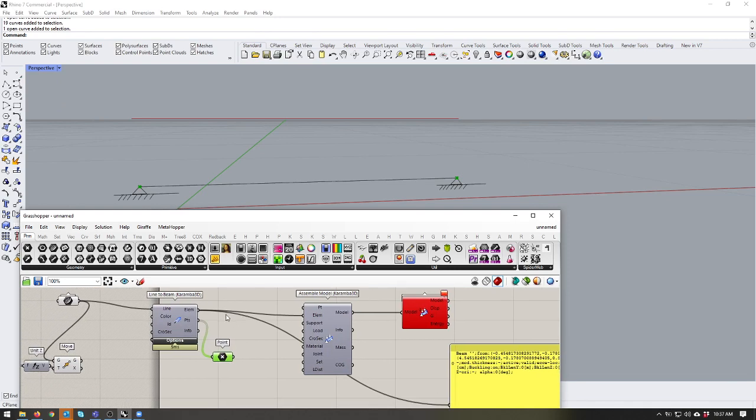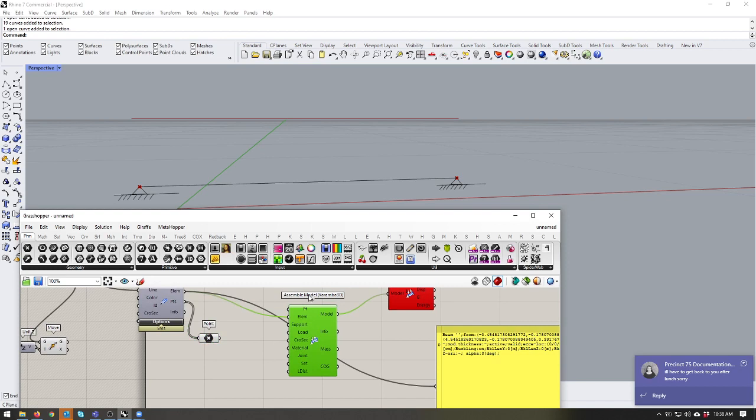So what I've done is I've drawn a beam, I've put it in space, kind of in the atmosphere somewhere, and I've just said calculate. And the system says, I'm not designed to work out how far the beam will fall when it's not supported. I must have a point of support. I need at least one point of support, and if that point is a pin support, then you're going to need more than one, or otherwise the thing's just going to flop about. So it wants your structure to be sensible. You can see here in the assemble model section, there is a support input.